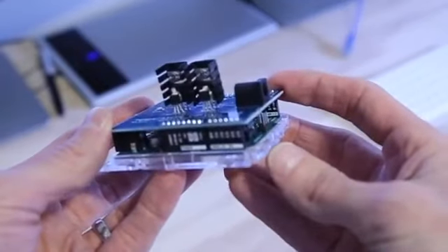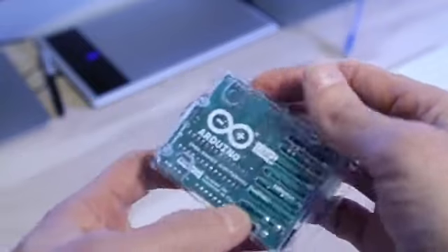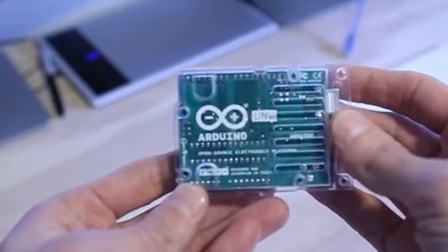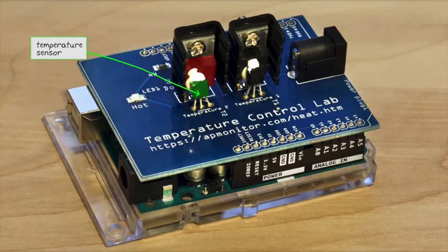We'll be able to learn a lot from operating this hardware, but to tie it back to our spacecraft, you'll just need to use a little imagination. Let's walk through it in more detail. There are two sets of heaters and temp sensors, but we're just going to use a single one for our test. The temp sensor is highlighted in green and it's bonded to the heater in red with white thermal epoxy in between the two. The thermal epoxy creates a good conductive path between the heater and the sensor.